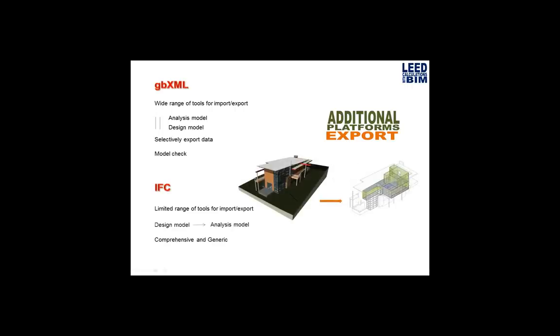The IFC file format, you export your data, so you're actually getting geometry plus parameters about the geometry. Yep. GBXML is just the data about the geometry, not the geometry, correct? The GBXML, yeah. What Robert just said is that the IFC exports all of your data from your model, right? So the GBXML is doing a selective export of just certain elements that it's going to recognize, but the IFC is going to take everything.